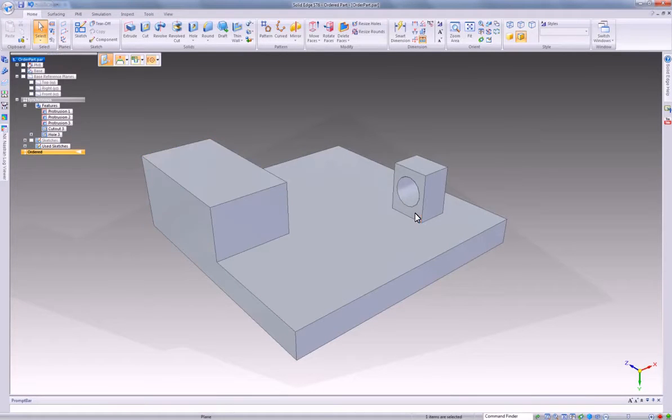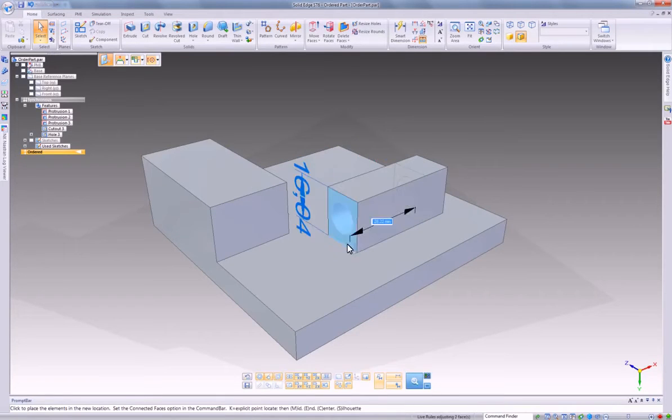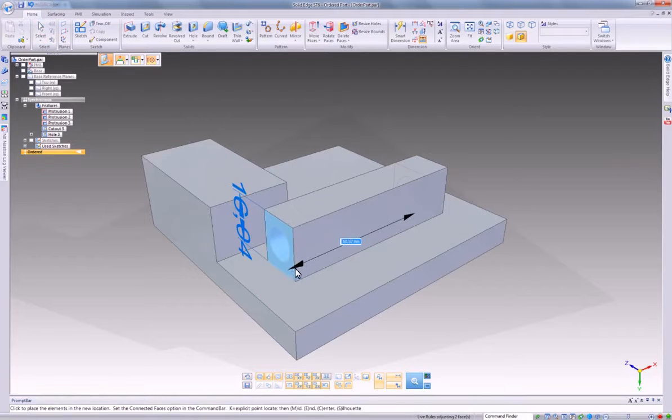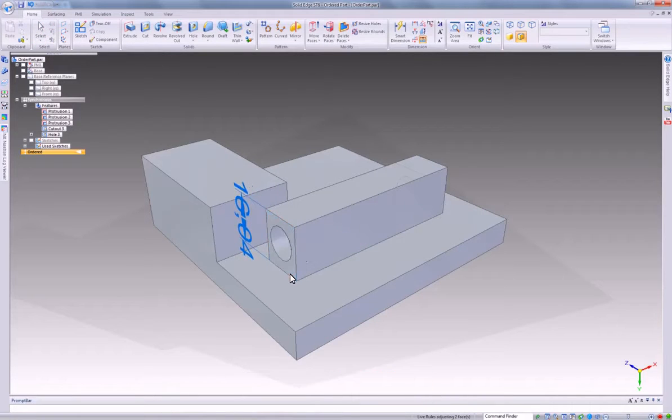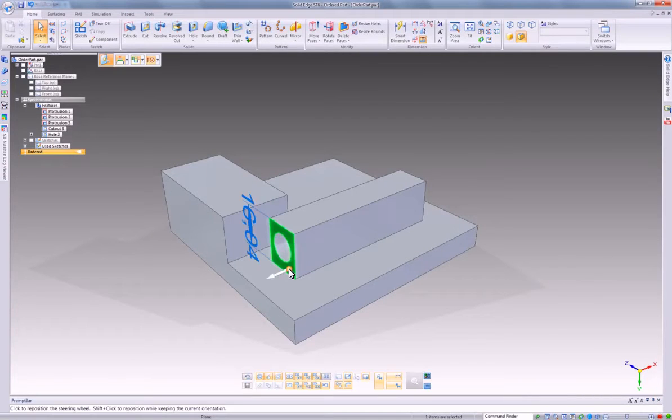So even in this case, yes, we're able to achieve it in this simple example, but there is an impact to the user: when they did that, they lost all their features related to this. And even though we can now get the predictable result, we can also go in here to rotate the faces. For example, we can just select this face, go ahead and click on the pen, and we can get it to change its orientation axis there.